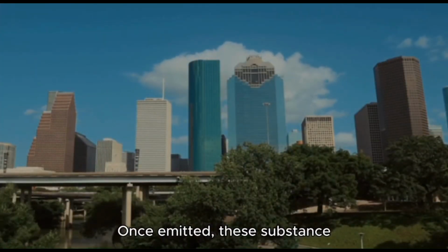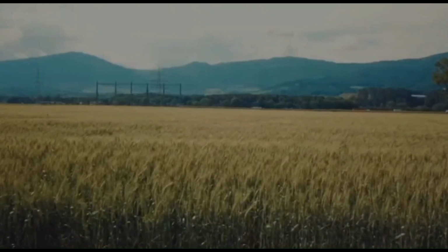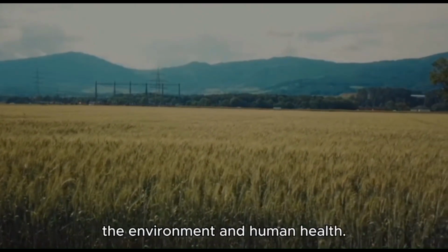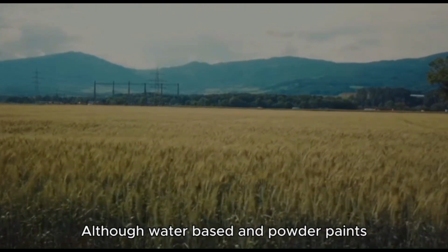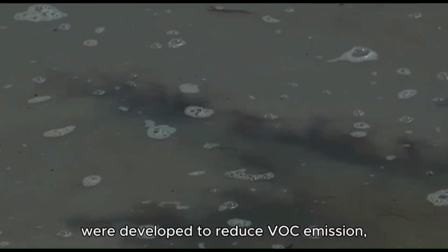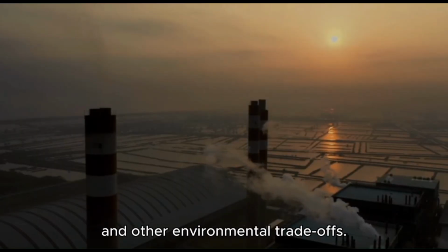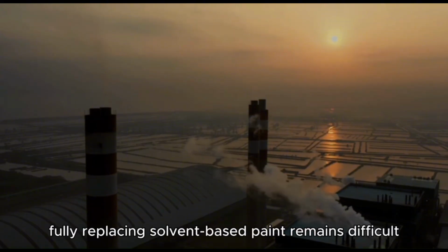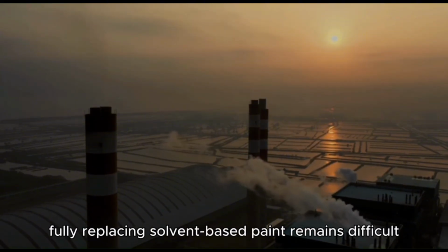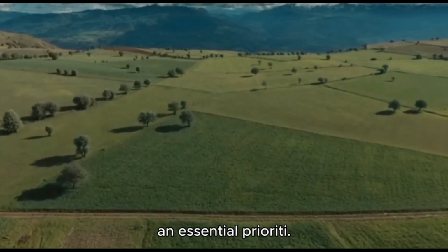Once emitted, these substances contribute to air pollution and ozone formation, posing risks to both the environment and human health. Although water-based and powder paints were developed to reduce VOC emissions, they introduced technical challenges and other environmental trade-offs. As a result, fully replacing solvent-based paint remains difficult, making VOC emission control an essential priority.